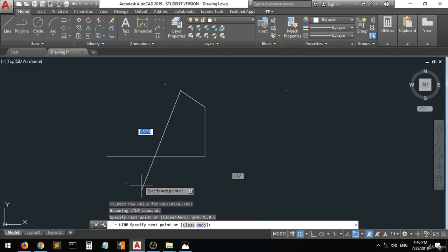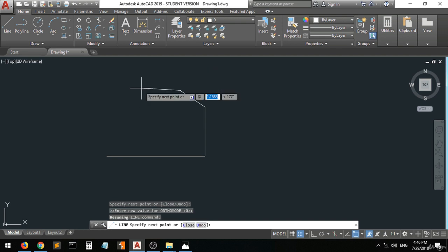You can enter it with either the coordinate entry or the polar entry. Let's do it in both. I will start with the polar entry. We type the at sign, the length of the line, which is 1, then a smaller than sign. Then the angle of this line will be what?